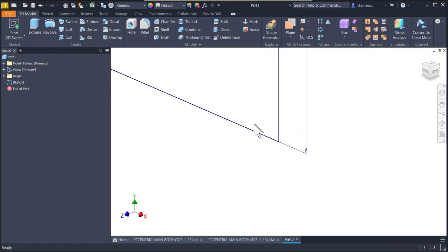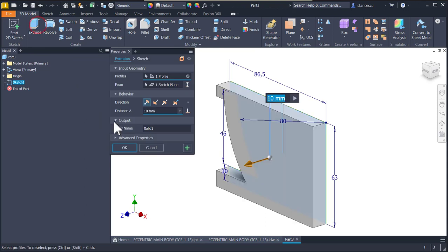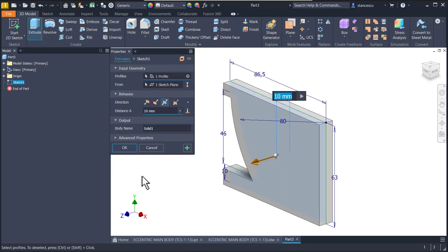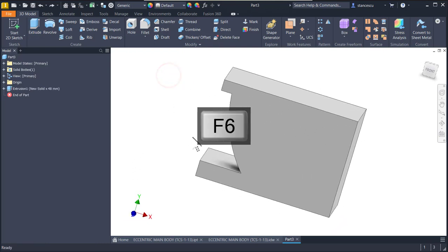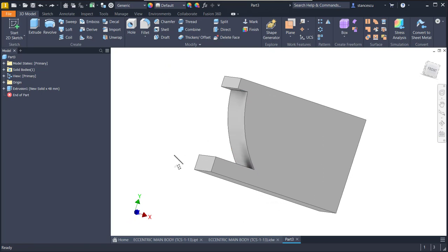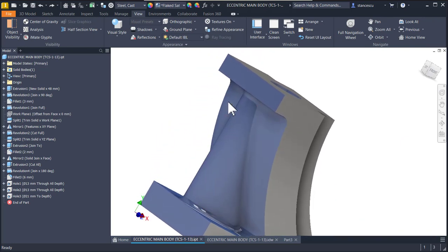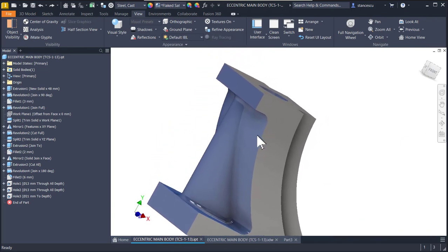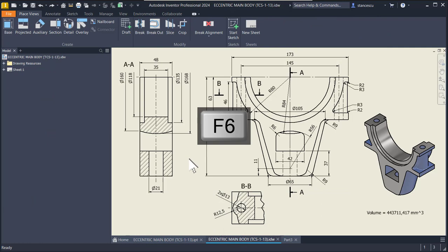Good. Finish sketch. The thickness is 48. Extrude. Symmetrical. 48. And we have the first volume. Now we have a cylinder here, but our object has a somehow spherical face, not cylindrical. Dimensions are interesting. 168 maximum, 160 minimum.